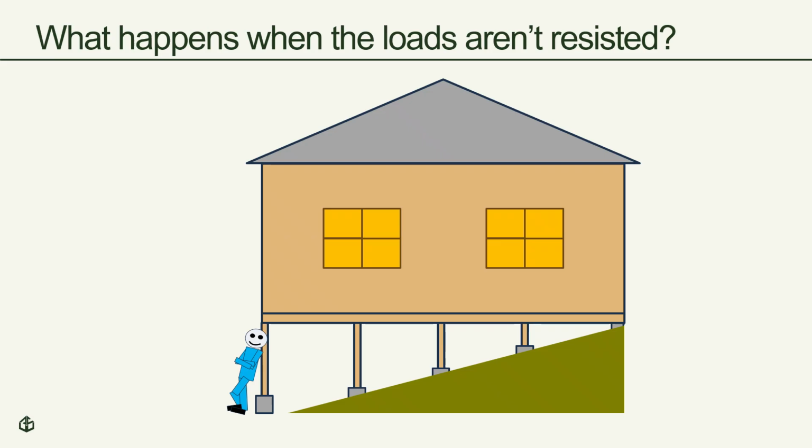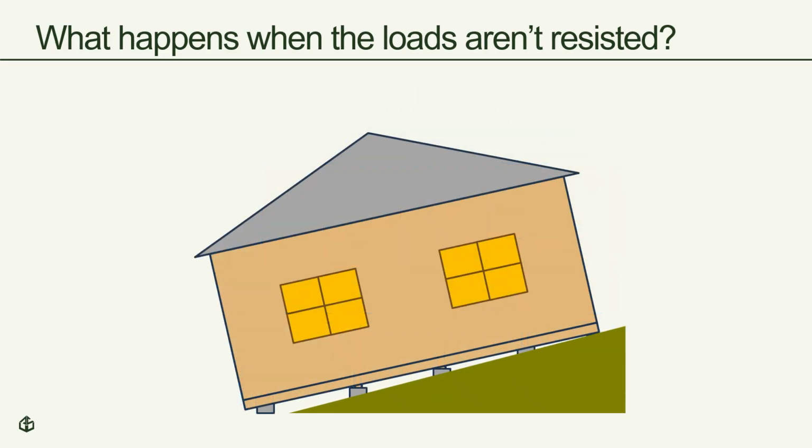Remember when we discussed limitations for hillside construction? Regardless of the slope of the hill or the height of the posts, you now know the code always requires engineering for posts and piers supporting brace wall panels. Without proper engineering, there is no way to know the loads will be resisted and the building is subject to failure.